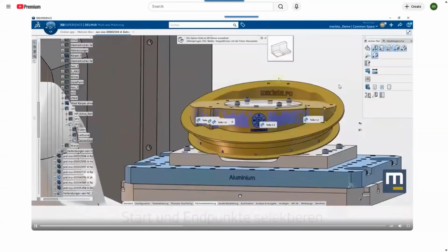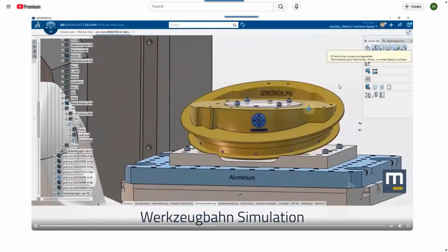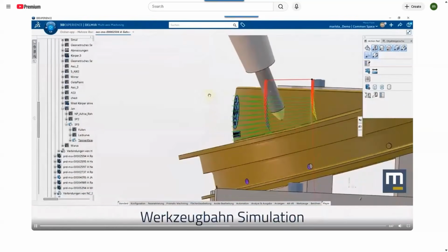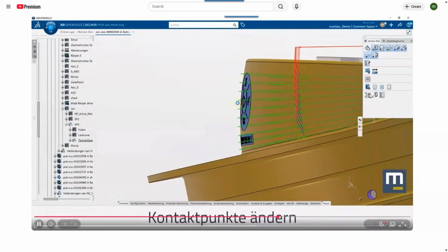The key here is I showed you turning with machine simulation. Here's an example of advanced milling with machine simulation to be able to guide that barrel cutter down that face and create the smooth surface that we want. So we'll go through and we'll run it. Here you can see we're able to analyze and verify where that barrel is going to cut down along that path to make sure that it clears where we need to be and get the finish that we're looking for.